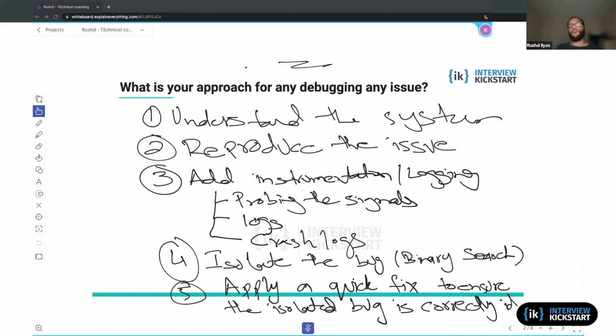But all of this is not free. It has some cost. In the case of asserts, usually there is a string, like a printf associated with that file name and line number, that gets stored in the code space. So each assert you use adds whatever that number of characters is, could be 4 to 32 bytes of string.